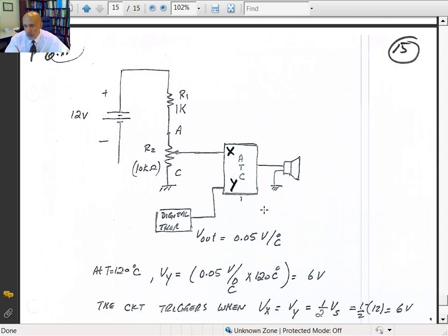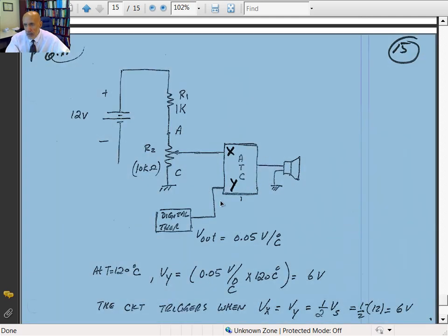But it says that the X and Y inputs each have an input resistance of 10 megaohms. That is, each appears as a 10 megaohm load to its input circuit. The reason you want that, from problems we looked at so far, is that if this circuit does not have high input impedance, in other words, very high resistance as a load, then you will have a loading effect.